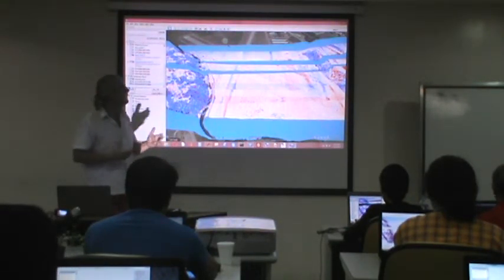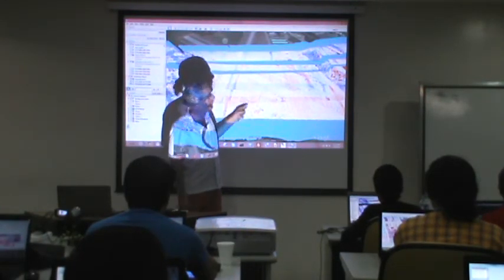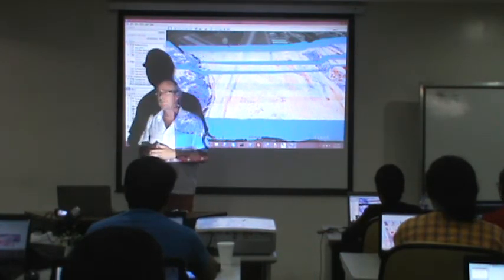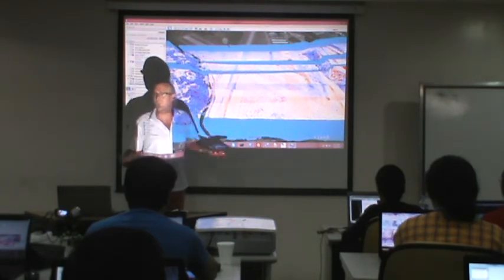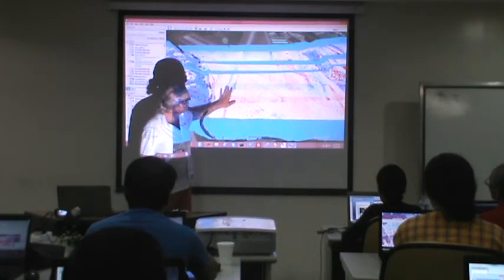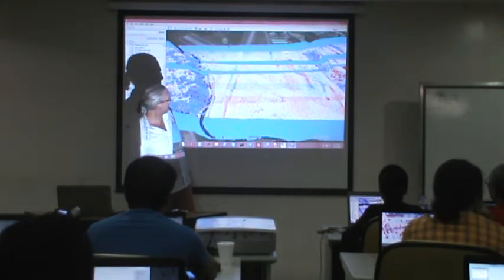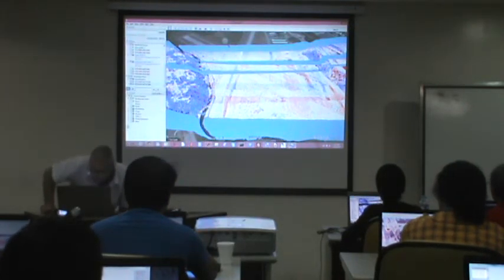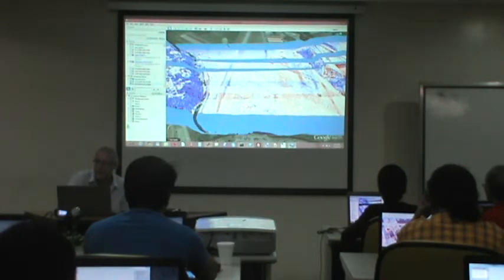For a more rigorous check, you would compute the actual difference values, especially in the open areas, and then look at the distribution of errors. I think in this case, this was a survey done quite a few years ago. The scanners weren't quite so good then. This was a very good scan because it had only slight misalignments here. And here's again. There's grassy patches, and here you see little shrubberies, but on the main runways, it's okay.